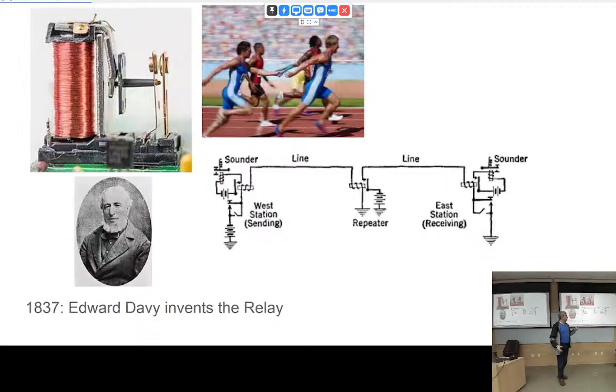So the key idea here, which is important for chip design, is that this is only possible because the inputs are of the same kind of thing as the outputs. So if you have a device that has, for example, the input is a mechanical rotation and the output is electricity, or the input is electricity, the output is light, you can't connect several of these devices. So here we have currents and voltages as the input and currents and voltages as the output.